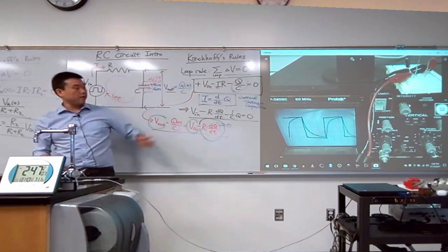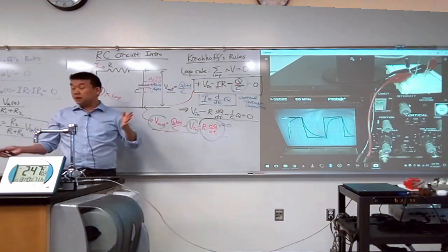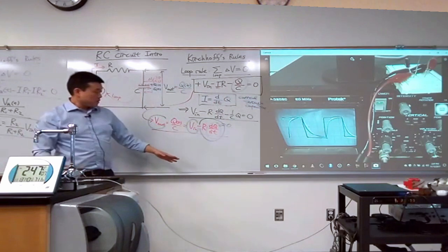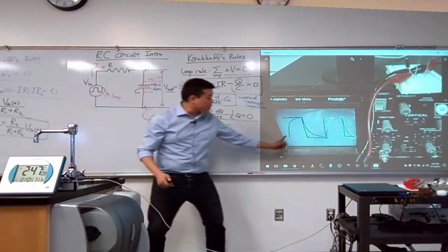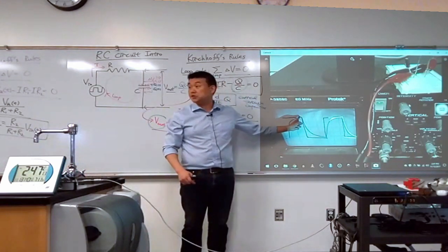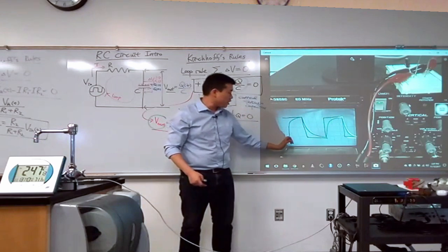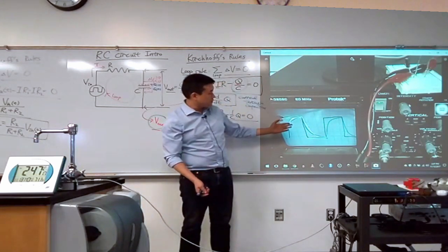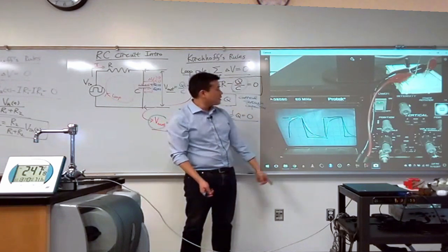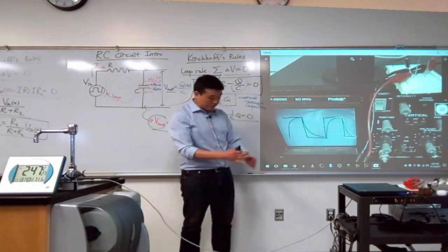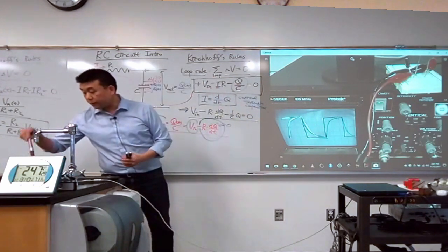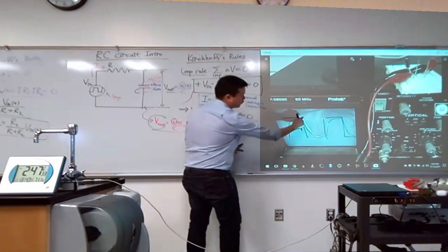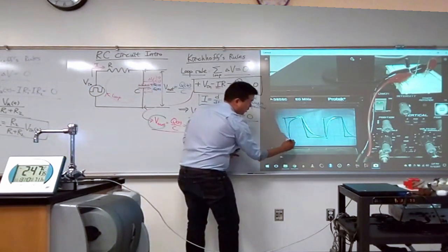When you run this at a higher frequency, you can describe it as the capacitor charging up from 0 to some value. If you cut it off too soon, so if the square wave period is too short, then before the capacitor has time to fully charge up, you cut it short.